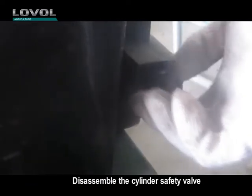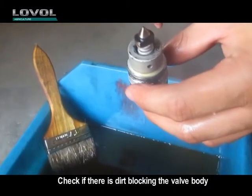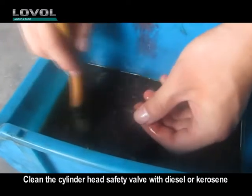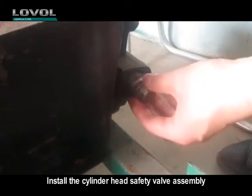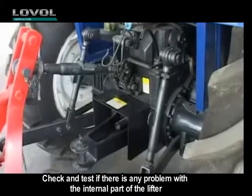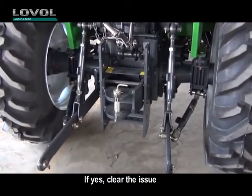Disassemble the cylinder safety valve. Check if there is dirt blocking the valve body. Clean the cylinder head safety valve with diesel or kerosene. Install the cylinder head safety valve assembly. Check and test if there is any problem with the internal part of the lifter. If yes, clear the issue.